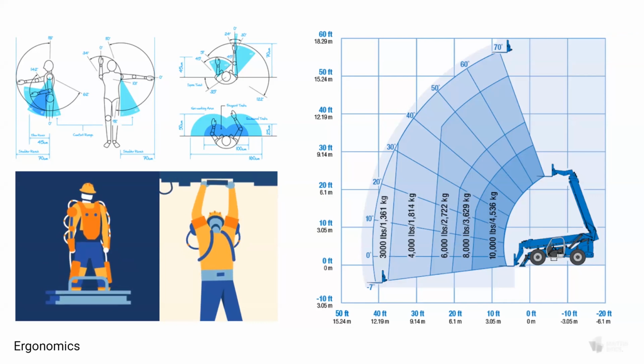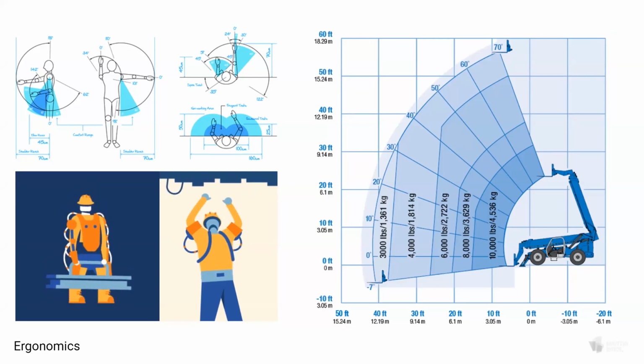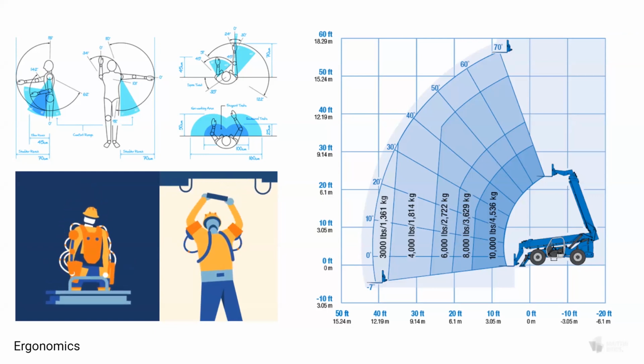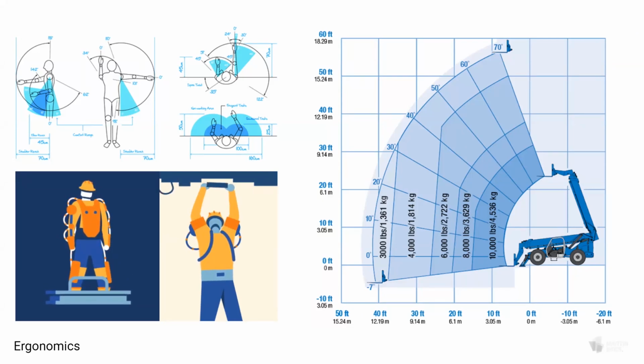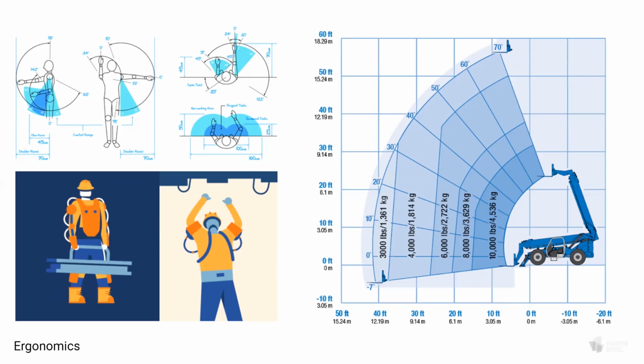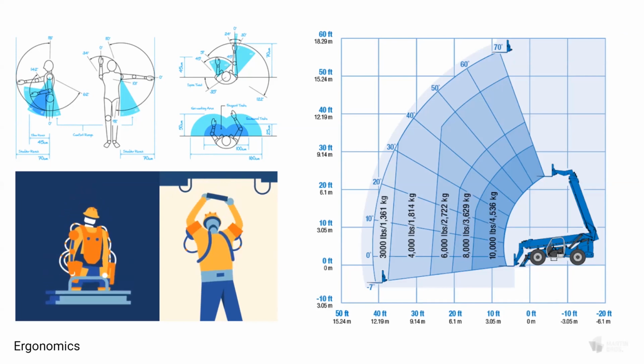Similarly, assembly lines are carefully studied to confirm that any given process falls within the, say, 5th to 95th percentile of human arm length and range of motion. These are hard constraints, and the clashes are real. When something falls outside of this range, we start having to design custom tools, a special wrench to reach into tight corners, or for us, custom clamps on the ends of the forklift.